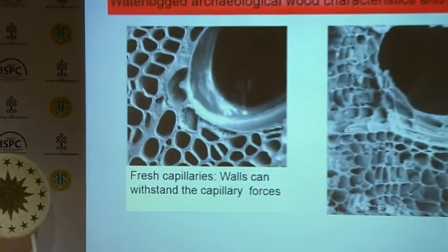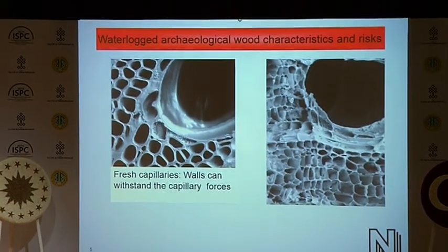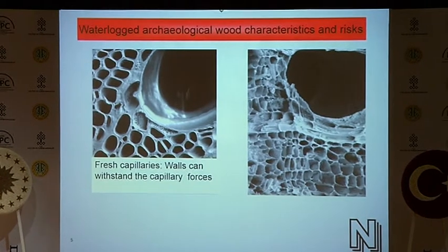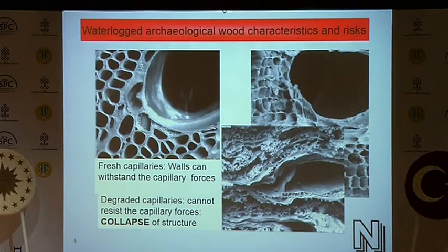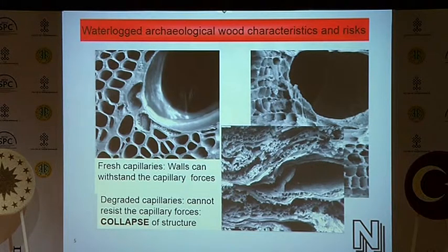This is how wood looks when it's degraded. This is a dry piece, but imagine that this structure was filled with water, and when water evaporates from such structures, the capillaries cannot resist the capillary forces, and the structure collapses. That is the main problem with wood.